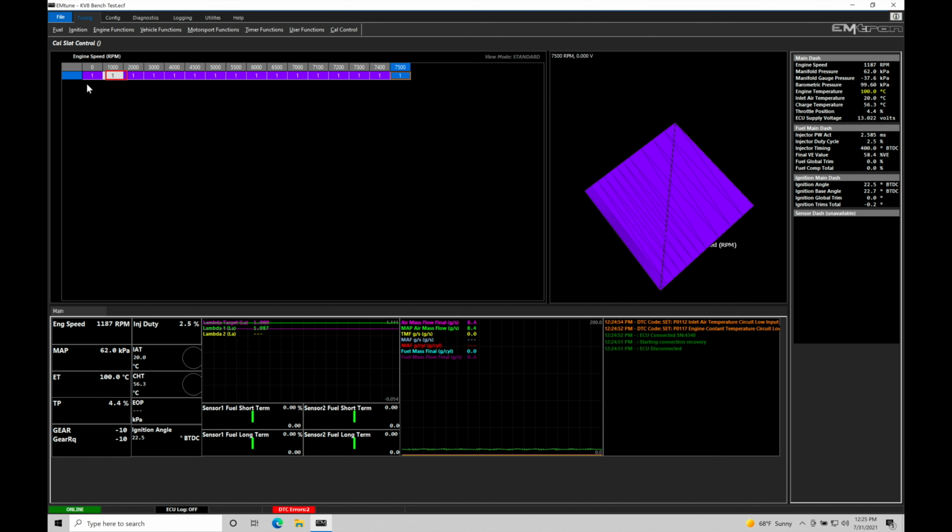Now in this case, slot 1 is going to be our first slot. We have up to 4 total slots, so we'll put a value here of 1, 2, 3, or 4, depending on the condition that we want to switch over to those specific slots. Now this table is set on engine speed, and then we have our slot position as a lookup against engine speed. Now most likely we don't want to do it based on engine speed. We want to do it based on either an on-off toggle switch or a rotary trim pot.